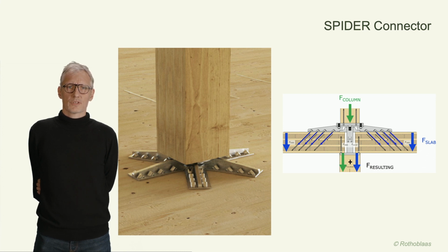And what about shear forces? Spider tackles this too, by reinforcing the CLT layers with inclined screws. As for flexibility, Spider allows for a large 7 meter by 7 meter grid, perfect for open floor plans.